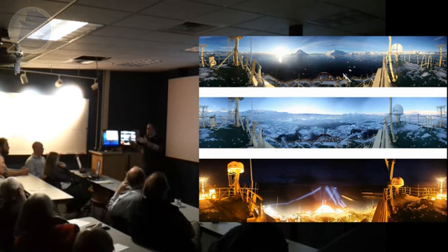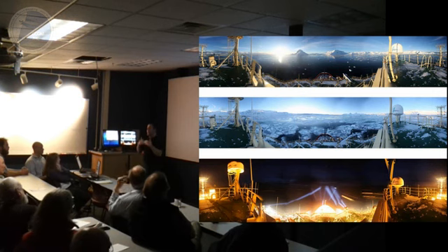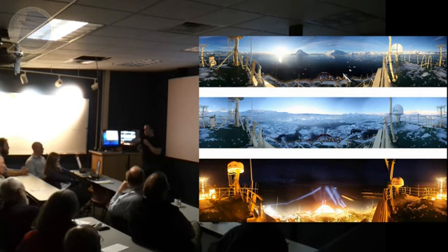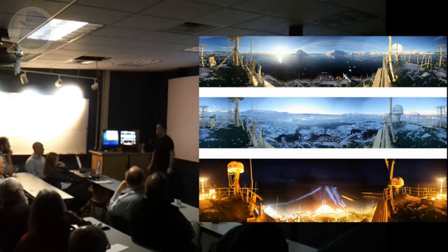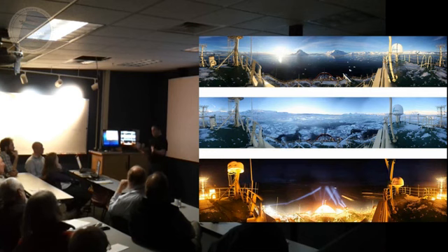It's the front-looking one. But that's okay, because the front-looking one allows me to see the stuff that it's looking at come at us, so it gets close. So I don't need a very high resolution of the stuff that's far away ahead of us. The side ones are the ones that are important because they will look out the sides where we're not going. So we're never going to get close to that stuff. The stuff that's ahead of us, we are going to get close to. So that's why you set up those narrow ones on the side, but keep the forward one as is.